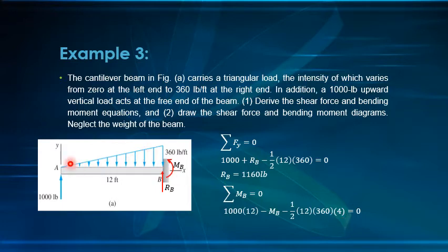The resultant for this varying load is acting at the 1/3 of the figure from the highest. Okay? Mula dito, 1/3 po siya. Doon nag-act yung resultant. Kaya, if we divide it, 12 divided by 3, that is equal to 4. Okay, so that will give us the value of MB, moment at B, that is equal to 3,360 pound-feet.